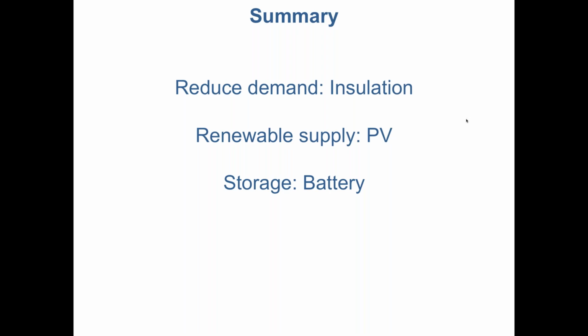We've had quite a bit of experience on battery storage, and that's interesting because battery storage doesn't save energy really. It just enables you to keep the renewable energy you've generated in the day and use it in the house rather than export it to the grid. So what you're saving is the cost of buying energy from the grid at whatever price, 15, 16p a kilowatt hour, rather than exporting it to the grid and getting a very low price. The cost benefit then is something like 200 to 250 pounds a year.